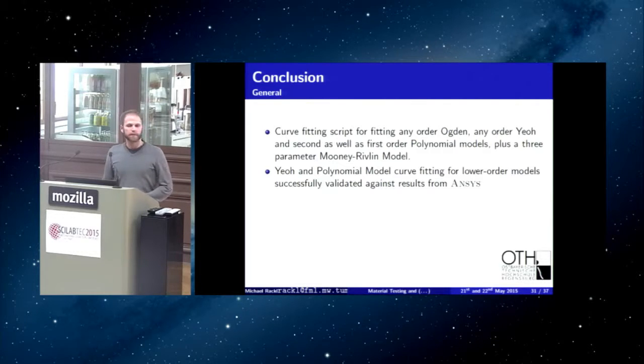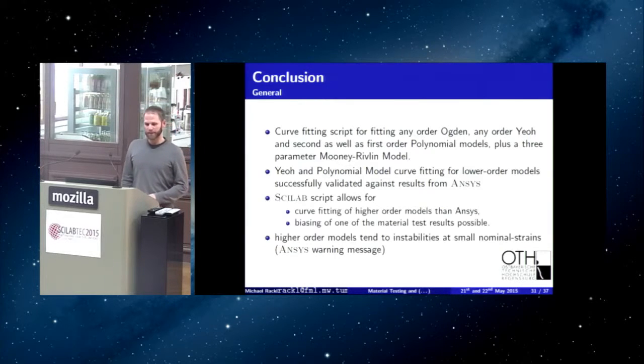We also validated the lower order results against ANSYS, which worked well for the Yeoh model as well as for the polynomial model. But one of the problems we had was that especially the higher order models tend to instabilities. And those instabilities can crash your finite element analysis computation. So even though we were able to fit these higher order models, we could not really use them because our finite element computations kept crashing.